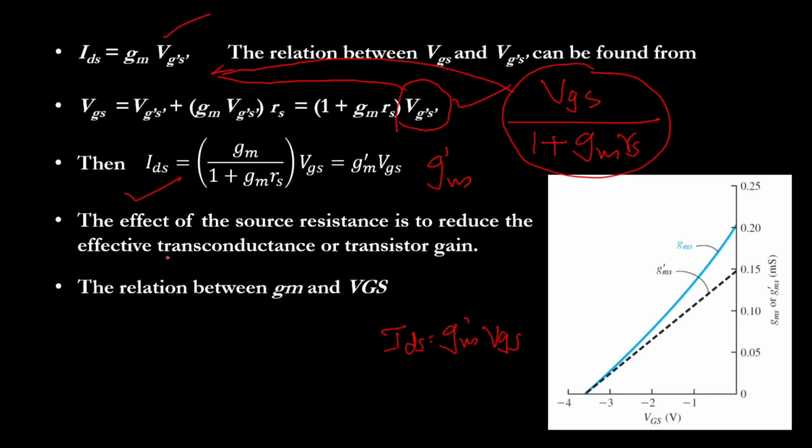So this is the technical term being used for representing gm. gm is nothing but the gain or transconductance. So look at this. This Rs value is available in the denominator. Since it is in the denominator, if the Rs value is increasing, what will happen to the total gain of the transistor? The total term, that means g'm, is going to reduce.